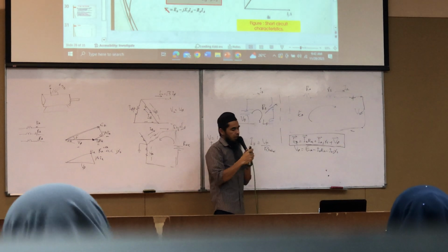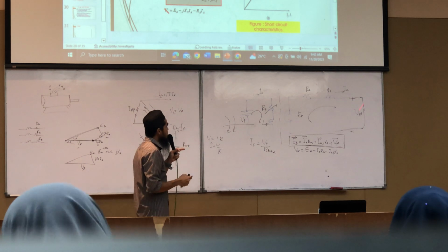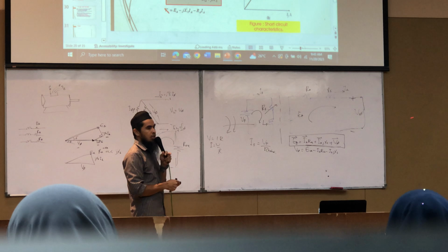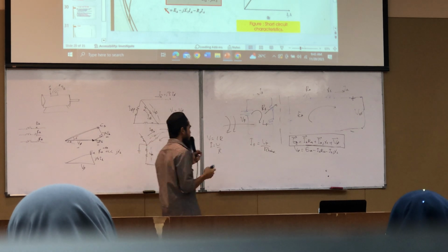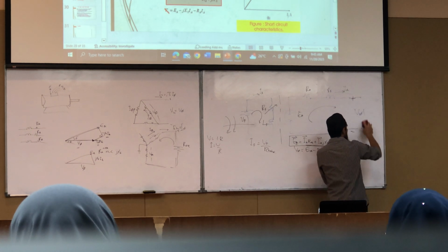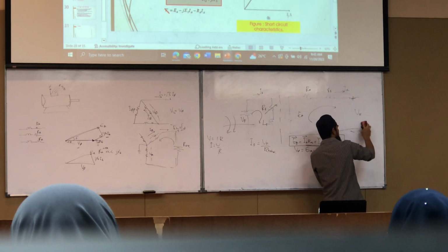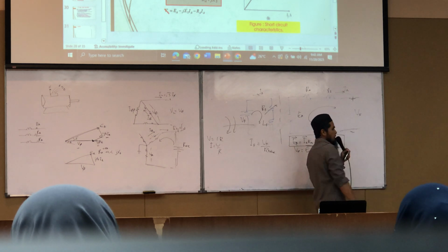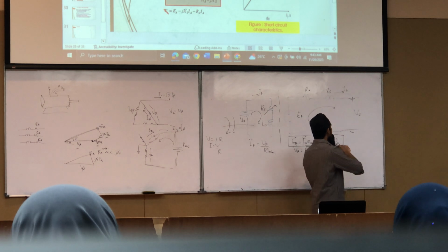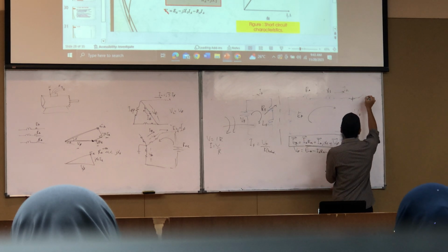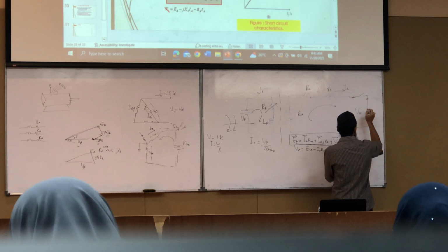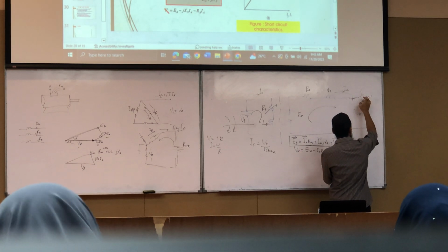But for this test, you cannot run it short circuited in the initial state, you cannot start with the short circuit. You have to run it until it reaches rated speed. Only then do you short circuit for a few seconds, then you release the short circuit. That's why we assign you all to have the on-off switch before you short circuit. You short the circuit, but this switch has to be controlled.